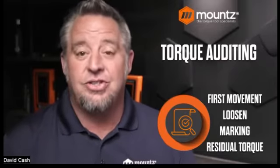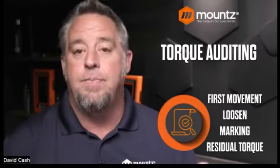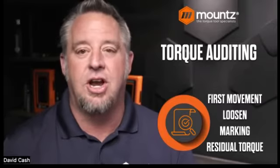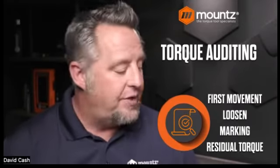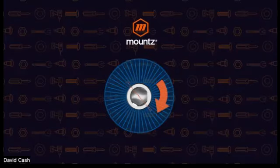Now, there is really no residual torque in a fastener once the tool has been removed from it. However, there may be some slight torque in that, some torsion, and we'll talk about that in just a second as well. If we take a look at the first movement test, we're going to take the fastener and turn it in the tightening direction a few degrees of movement. Anywhere from about 3 degrees to 10 degrees of movement is where we would like that particular fastener to go. There are some issues with this type of test.